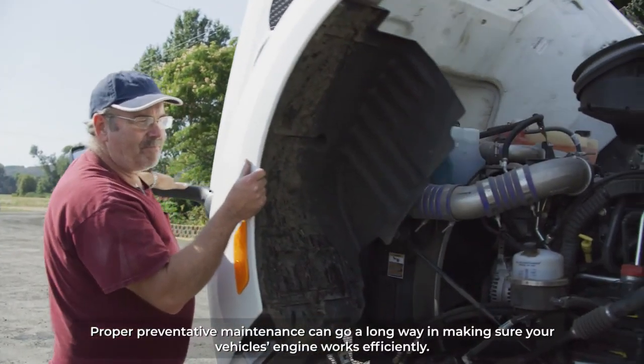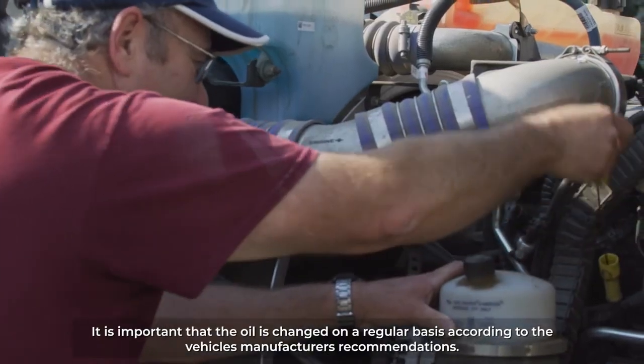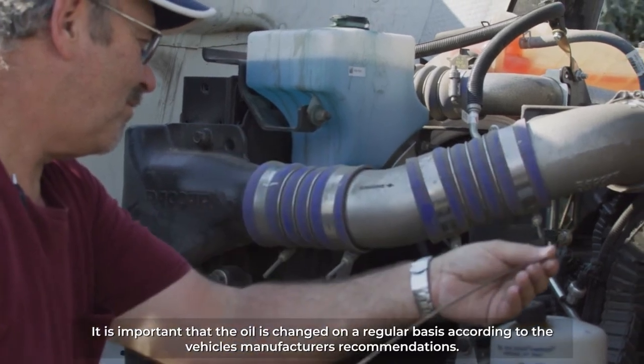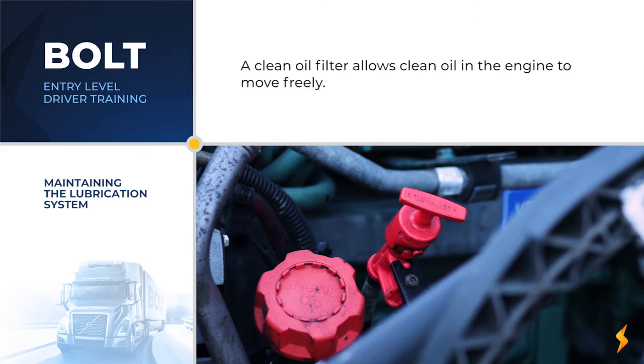Proper preventative maintenance can go a long way in making sure your vehicle's engine operates efficiently and effectively. It is important that the oil is changed on a regular basis according to the vehicle's manufacturer's recommendations. As part of the oil change, the condition of the oil filter should be assessed. The oil filter is where the dirt and other contaminants that the oil removes from the engine are deposited. A clean oil filter allows clean oil to flow through the engine more freely.